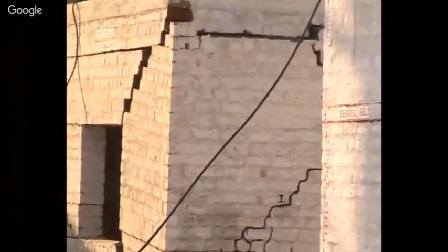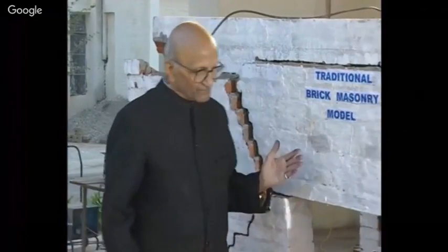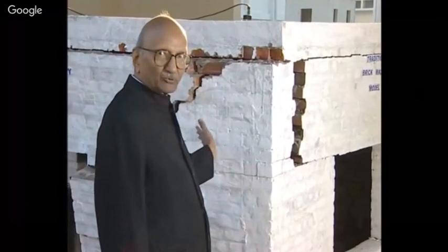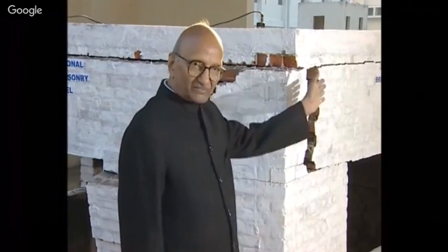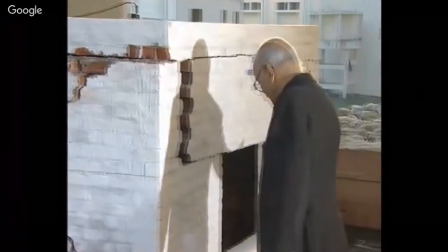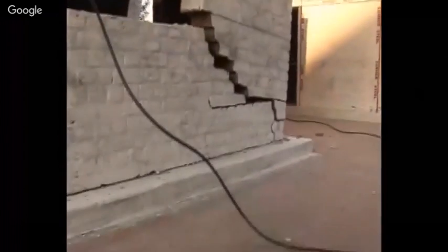This is the wall in the same line as the direction of the shock. So this has the behavior of out-of-plane bending. Now as we go, we see here how this wall tends to fall out. And then when we come to this wall, this shows different behavior than this particular wall, because this is now in the position of a shear wall. And a shear wall has a behavior of the shear failure, as we can see here. It's a diagonal tension failure. So we see here that this unreinforced model constructed in the traditional manner is failing.